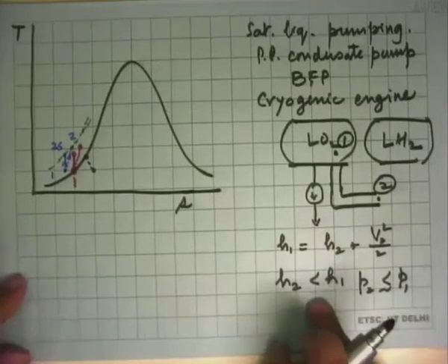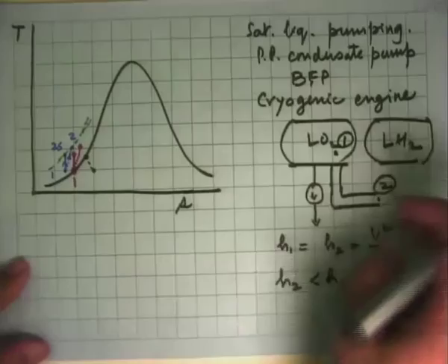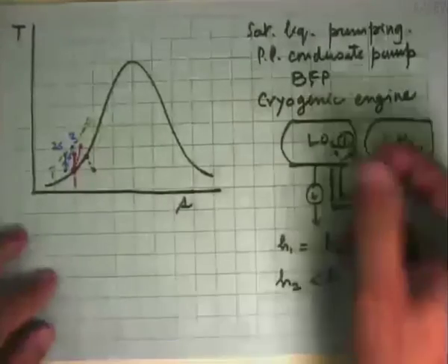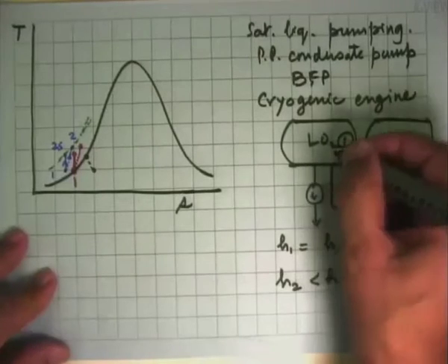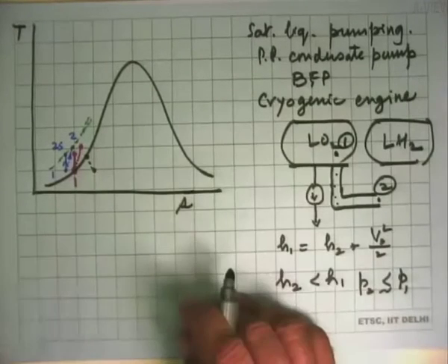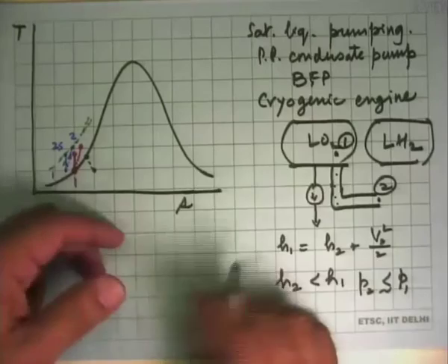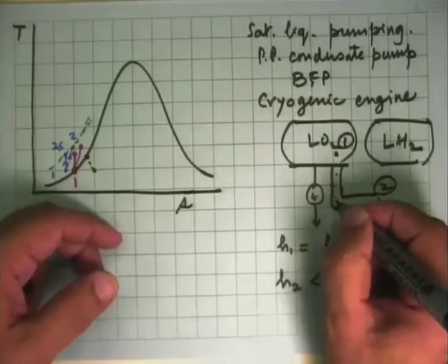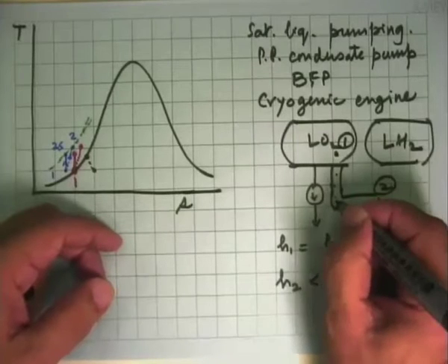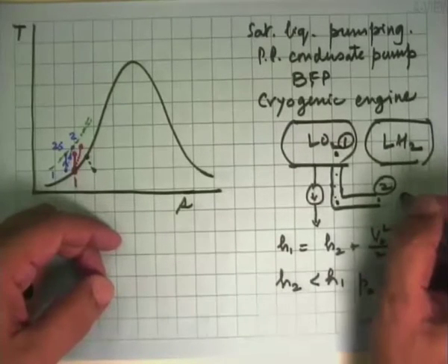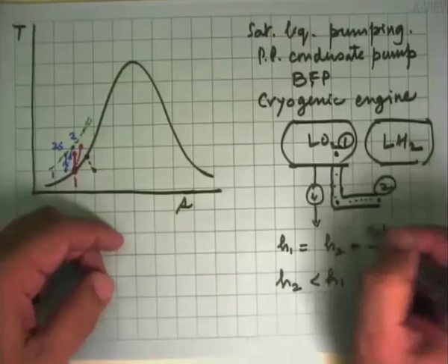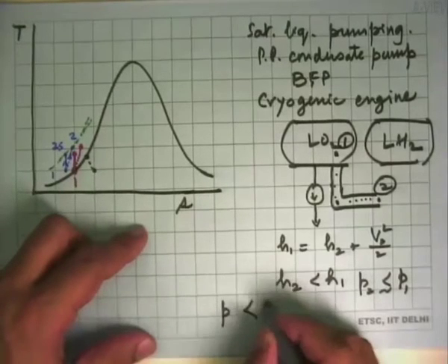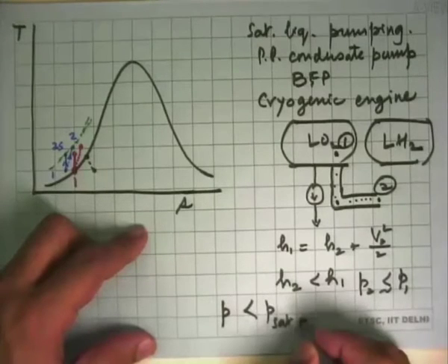Vapors, as you have seen, have a very large specific volume, suddenly the whole thing becomes crazy and the engineering becomes very difficult. And so we have to ensure that we give at least some minimum static head, so that this is saturated liquid, but as it goes down, the gravity head rho g h adds on to it, so the pressure here under no flow will be more than the pressure here, so it will be slightly subcooled, slightly compressed liquid. Then as you pump it through the pipe up to the inlet of the pump, the pressure drop will take place, but at no place do we allow the pressure to be less than P sat at the given temperature.